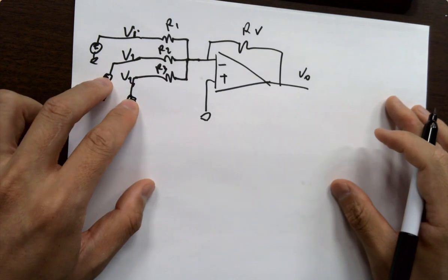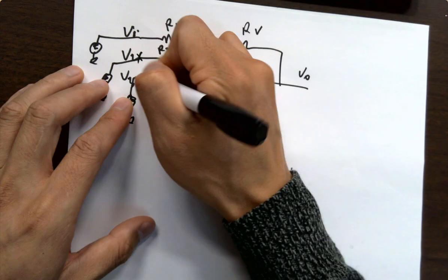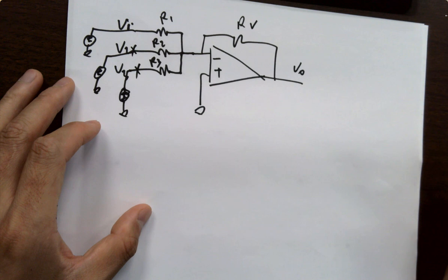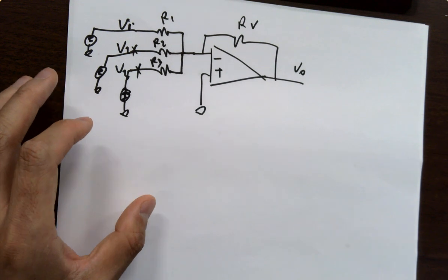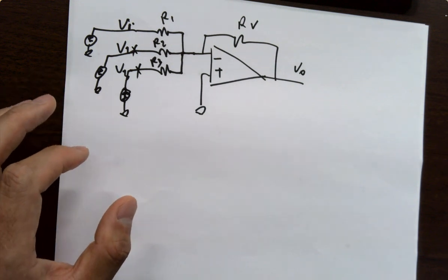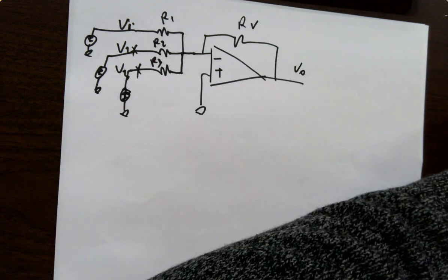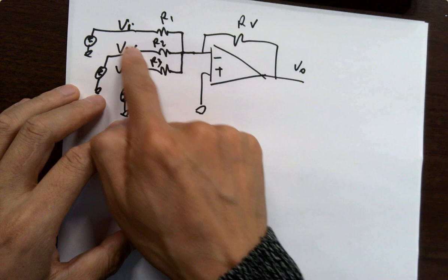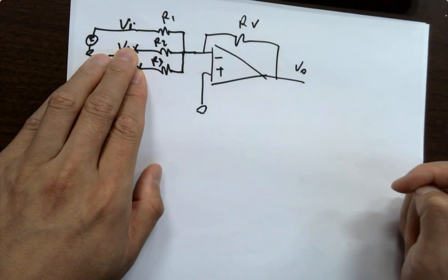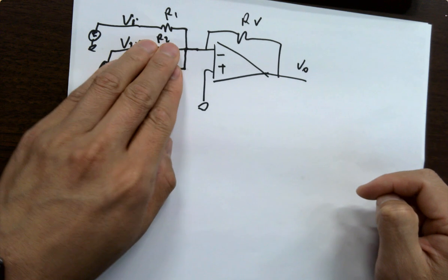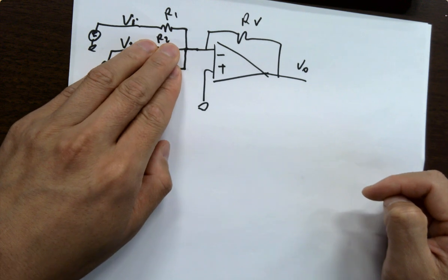If these two are off, does that mean that you have a disconnected circuit or it's shorted to ground? Gotta be clear. No, it's actually not. It should be shorted actually, but it's not. It's telling you that they are disconnected. It's a floating wire. It's not doing anything. No current. So what you have to do is ignore it. It's gone.